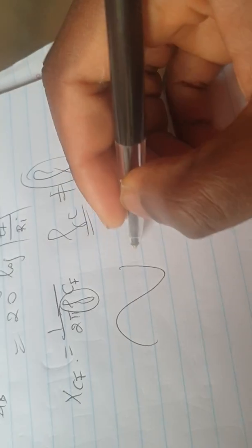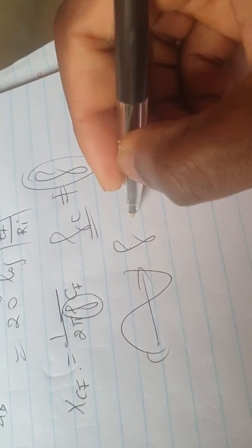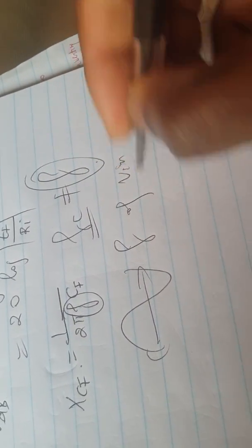So F is the frequency of Vin, while FC is the cutoff frequency of the amplifier that we calculate. But F, being the frequency of the signal Vin, is what we are given. It's the frequency of the signal we're trying to amplify. So when the signal we are trying to amplify is DC, of course, F is equal to 0, right?